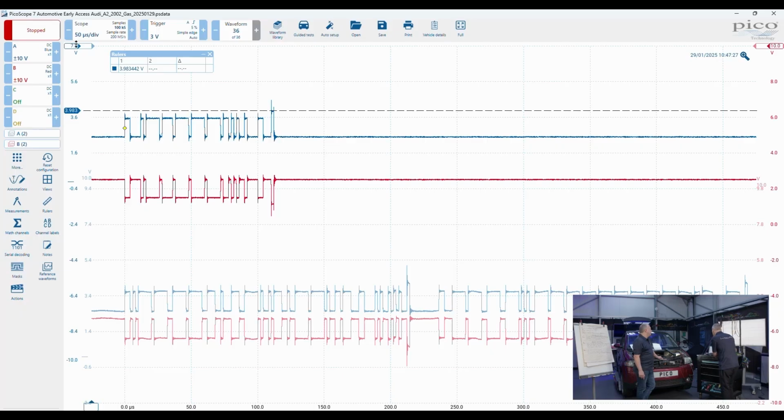So on that, if we bring these 2 rulers down, if we would say that that would be what we class as our signal top, sort of a bass top if we exclude the ringing and the overshoot, we've actually got an increase in amplitude of 435 millivolt. So don't think by any means that's a fault. That's actually what we're looking for. We want to see the acknowledge bit at the end of the packet greater, because all ECUs on the network have acknowledged receipt of that message and have sent out that signal, which ultimately increases the amplitude.